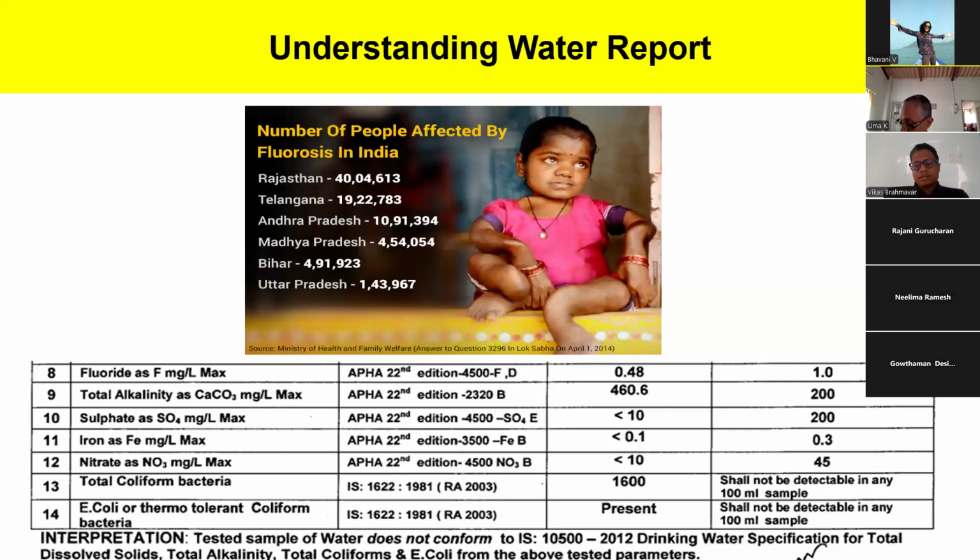So we thought we'll just get the water tested, because 1 year ago in the same region we had got the water tested and it had some 12 ppm of nitrate. So we got the water tested again. Surprisingly, around 312 ppm of nitrate was there. The TDS was only 700.